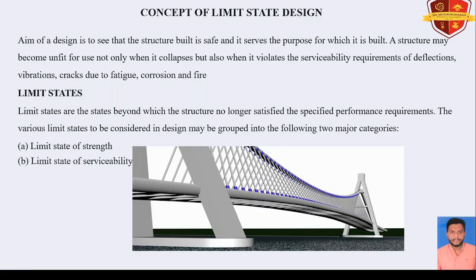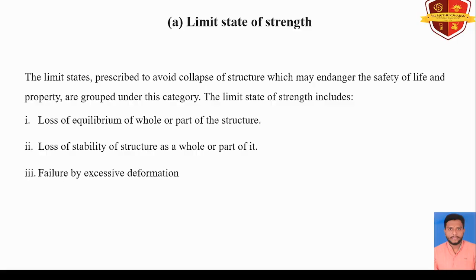Two types of design are available. One is limit state of strength, another one is limit state of serviceability. Limit state of strength includes loss of equilibrium of the whole or part of the structure, loss of stability of the structure, and failure by excessive deformation.